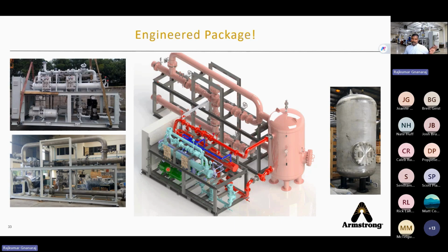If there is no load, the heat pump understands that I should not generate any hot water, and then the compressor trips off. If the compressor goes off, it takes 3 to 5 minutes to switch back on. So it's very important that we know how the heating load swings. If it's going to vary a lot, it's better to have a buffer tank for two reasons. One, to store at least 5 minutes worth of thermal energy in case the heat pump is not running. The second thing, this tank will provide a stable return water temperature going back to the heat pump. That will keep the heat pump healthy. So for those two reasons, we need a buffer tank.